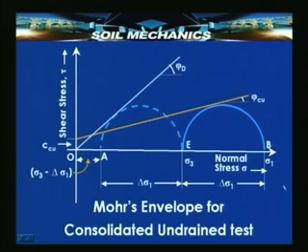The corresponding Mohr's diagram, if we take a look, the continuous line thick circle represents the total stress circle, that is the total stress sigma 3 applied and the corresponding total stress sigma 1. If we know the pore pressure, which incidentally is equal to delta sigma 1, that is the additional axial load applied, that means the pore pressure is known in this particular test.